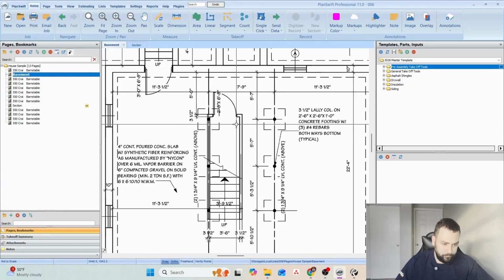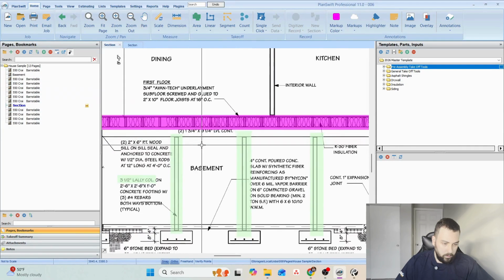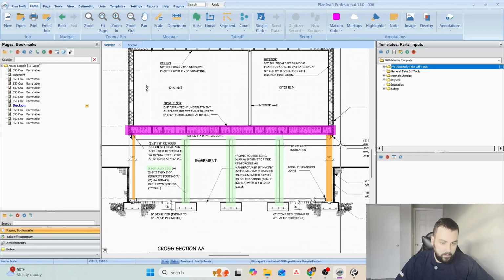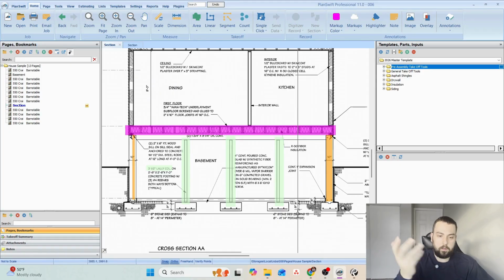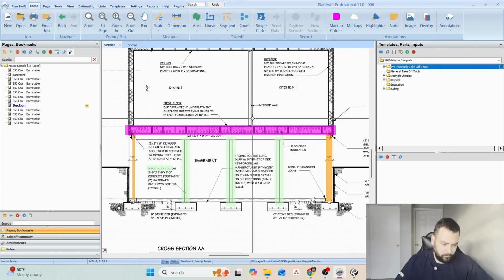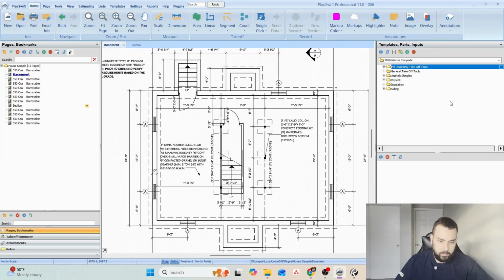Okay, all right. Yeah, it's not carrying any loads. What is carrying the load on the basement is the outside footing walls, exterior walls, these lally columns, and these LVLs. Okay, so it's just a matter of wall closing. So let's consider that as a partition.